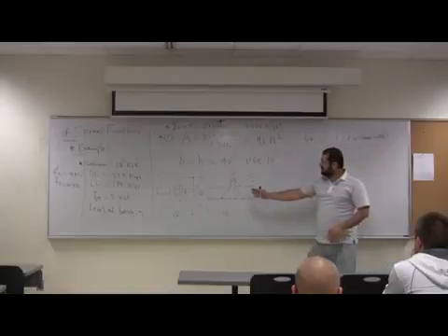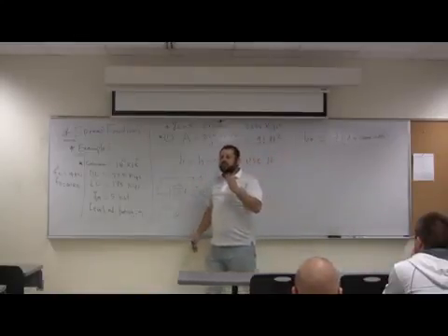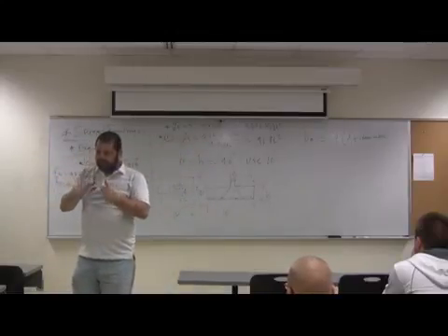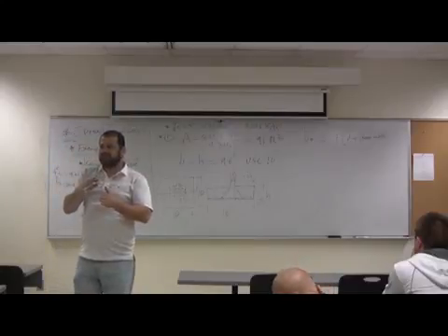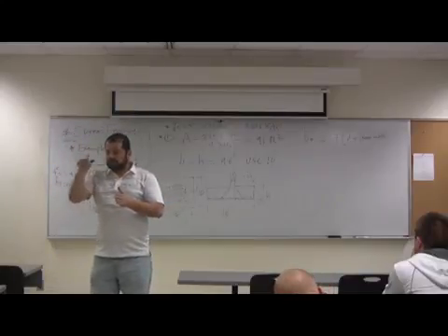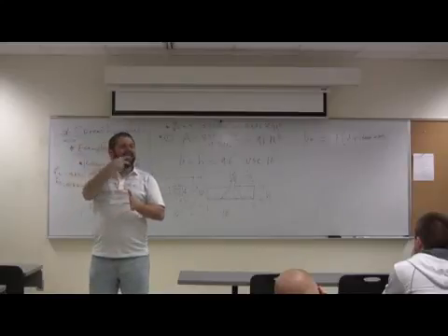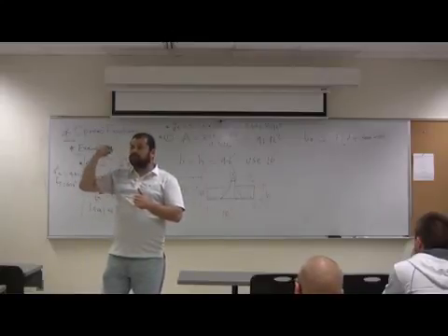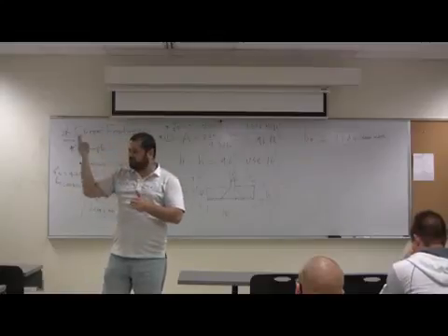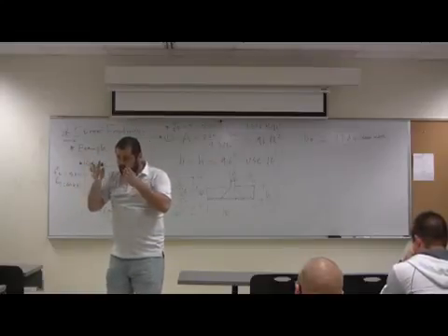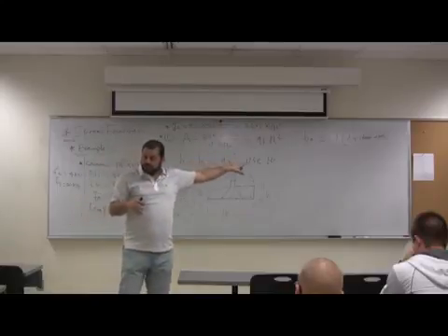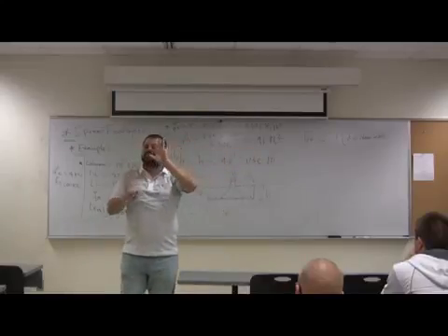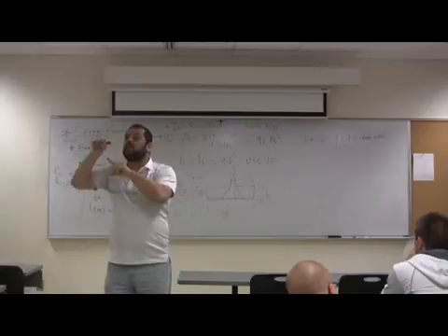We said the beam shear at D from the face of the support, the shear when you calculate at D from the face of the support, we compared with Vc, right? That Vc was equal to what, guys? 0.75 times 2 square root of f prime c b d. The guys found from lab experiments that the strength of the foundation for punching is way more than 2 square root of f prime c b d. So the strength of the footing in resisting the punching, that is the load within that box, is 4 square root of f prime c b naught d.